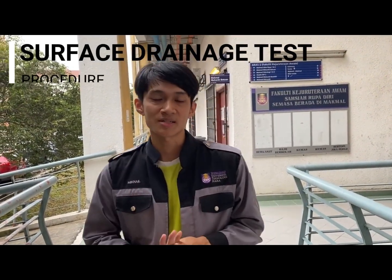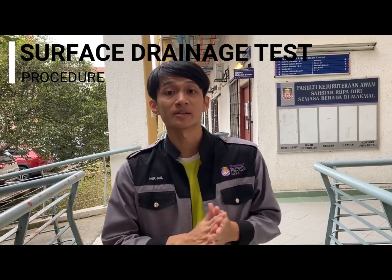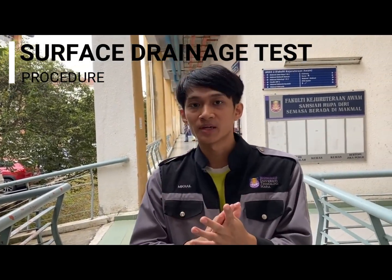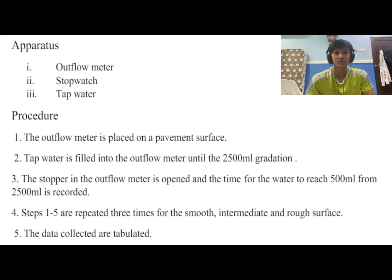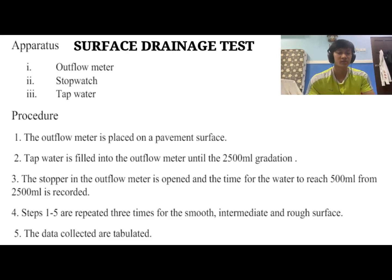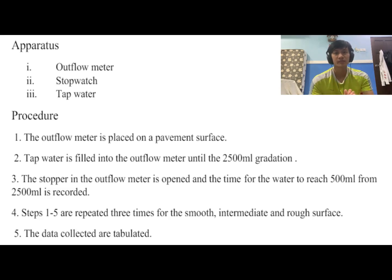So now we are going to conduct a surface drainage test to determine the surface drainage of different types of layers, such as smooth surface, medium surface and rough surface. So let's get into it. For the surface drainage test, the procedure is first we select a test area and then we clean the surface to make sure there is no debris or leaves or any obstructions that might affect water flow, because we want water to flow freely on the surface to get the exact surface drainage.